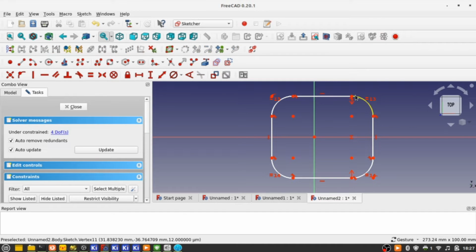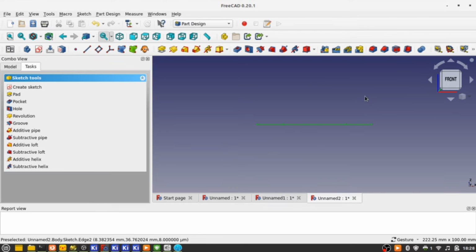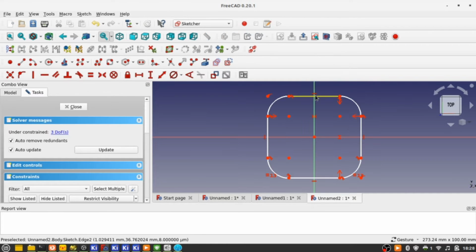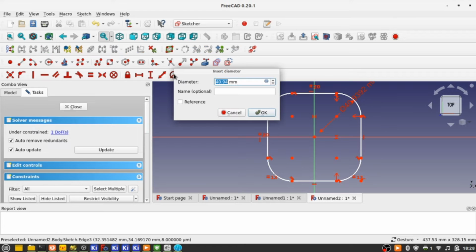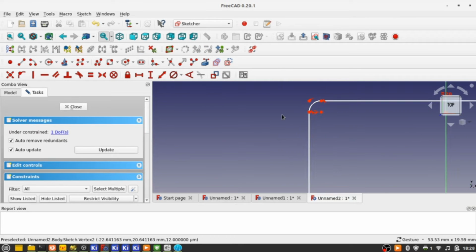All right, so we just want to make a rounded board, 100 millimeters on either side with 4 millimeter curved edges. I like 4 millimeters. It looks good with M3 hardware, like mounting holes. So we want this to be square, so we have to set those to be equal. They should all be equal already, so I only have to select one. Set diameter, 4 millimeters.